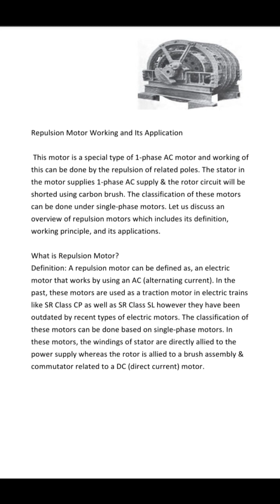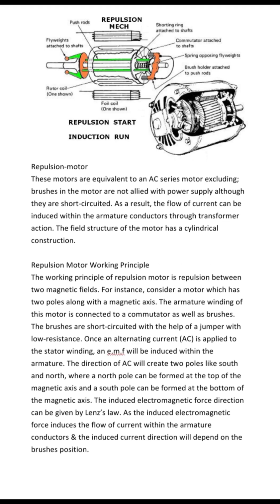The classification of these motors can be done based on single-phase motors. In these motors, the windings of the stator are directly connected to the power supply, whereas the rotor is connected to a brush assembly by a commutator, related to DC, which is direct current motors. These motors are equivalent to an AC series motor, except the brushes in the motor are not connected with the power supply, although they are short-circuited. As a result, the flow of current can be induced within the armature conductors through transformer reaction. The field structure of the motor has cylindrical construction.